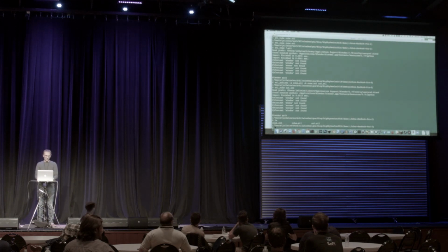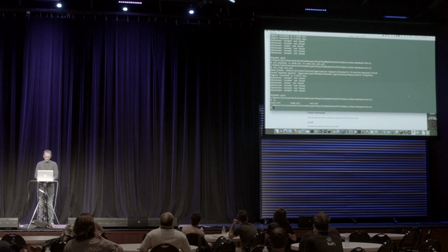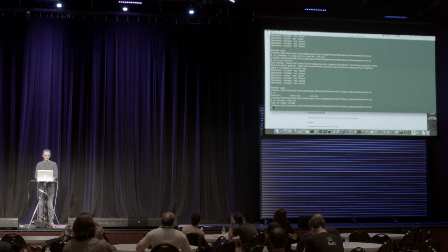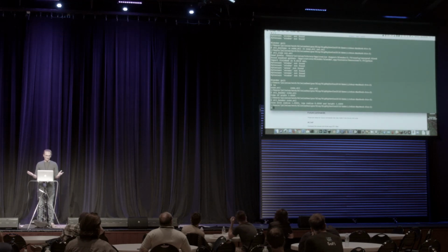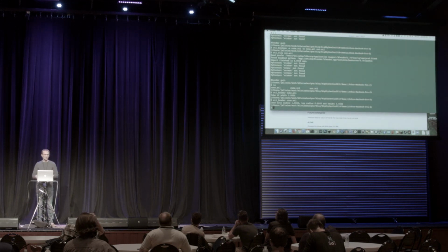Yeah, so then we can inspect that file. We can make this a little smaller. So STL Header of cube.stl. In that 80 bytes, there's just this string, cube of width 1. That was put in there. STL Header cone.stl. If you download things off of Thingiverse or something like that, you'll see all kinds of messages in here, like made with Rhino or made with whatever CAD software. So you can sometimes get a glimpse as to how someone made something.